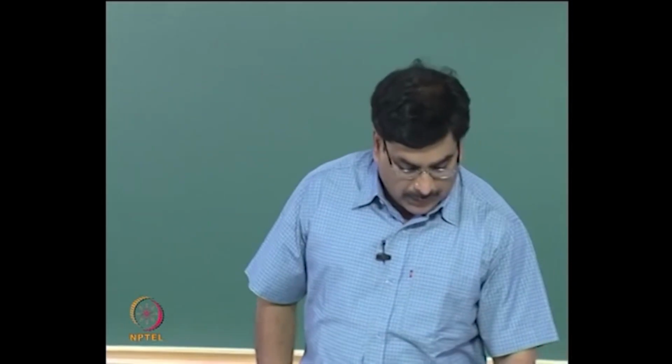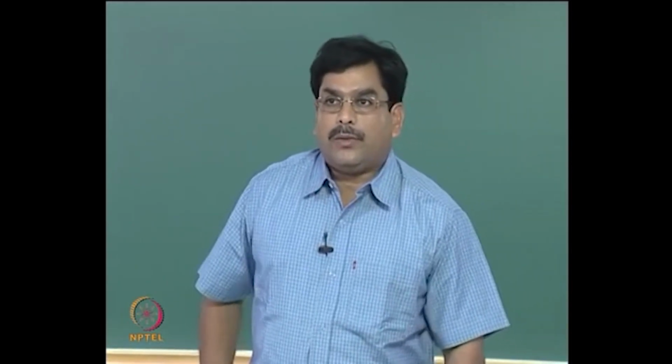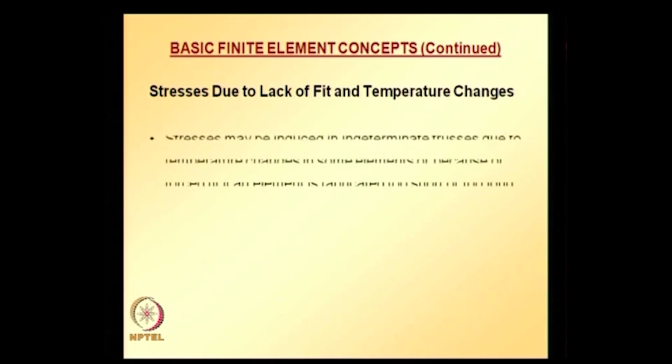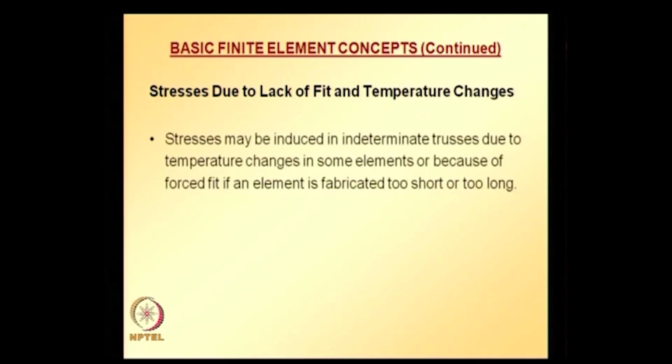looking at the stresses due to lack of fit and temperature changes in truss problems. Usually these stresses are induced in indeterminate trusses due to temperature changes in some elements, or because of force fit if an element is fabricated too short or too long. For both kinds of problems, that is, determining stresses in trusses due to lack of fit or temperature change, the procedure is almost similar.